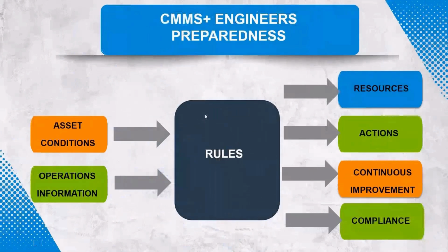All right, so I think in summary, what we're talking about today is basically using machine information, conditions, parameters, and also understanding the criticality of the process that those assets are being used in, and then based on that, putting together sets of rules that trigger based on either predictive potential faults that might be occurring, or just routine usage or utilization based work, rules that, once these actions are triggered, accommodate resources correctly, instructions correctly.